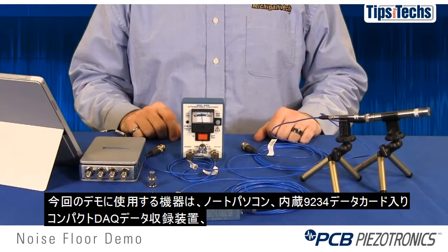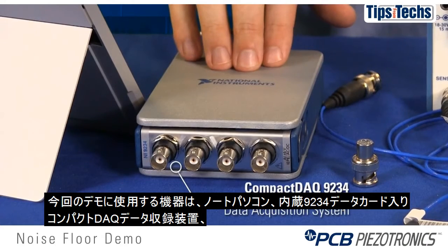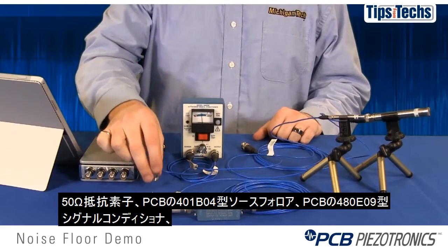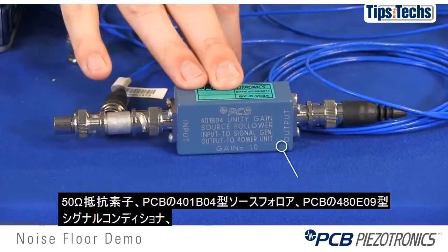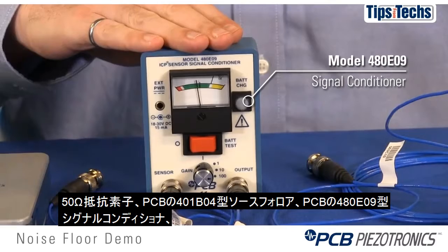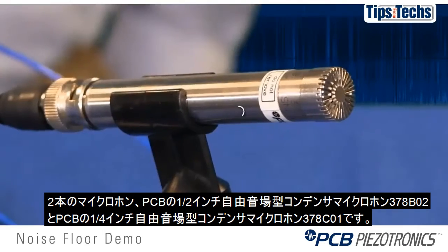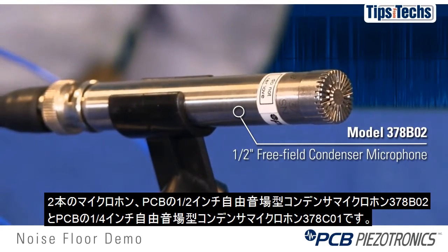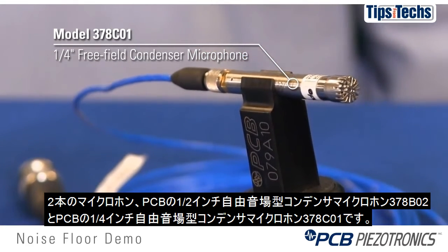So the equipment we'll be using for the demonstration today is a laptop, a CompactDAQ data acquisition system with a 9234 data card in it, a 50 ohm resistor, a PCB 401B04 source follower, a PCB 480E09 signal conditioner, and then two microphones: a half-inch free-field condenser microphone, the PCB model 378B02, and a quarter-inch free-field condenser microphone, PCB model 378C01.